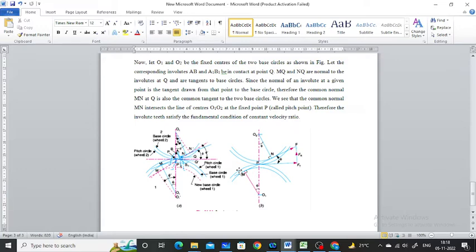This is not true for cycloidal gears, which require the exact center distance to be maintained. Now, in involute gears, the pressure angle remains constant from the start of engagement of teeth to the end of the engagement, because there is only one curve. Okay, it is necessary for smooth running and less wear of gears.